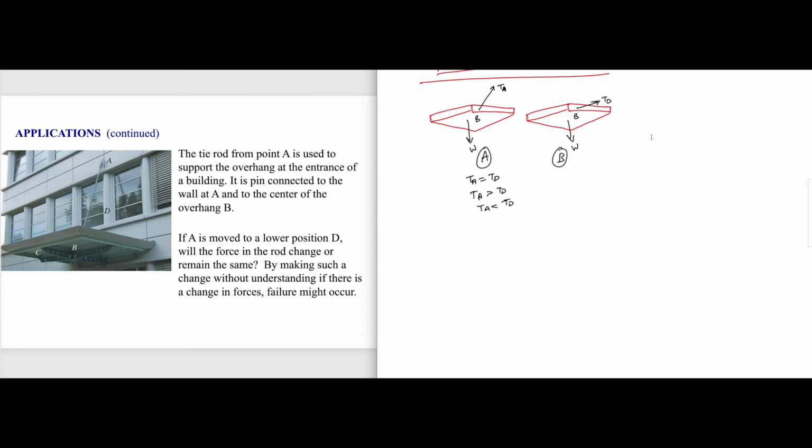The higher the slope of the rope, and this rope slope is bigger than this one, the lower its tension if it is supposed to balance the weight. Why is that? For example, apply sigma Fy equal to 0 for case A. Slope means theta.